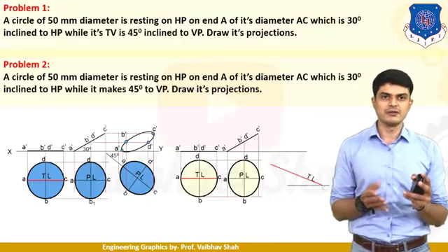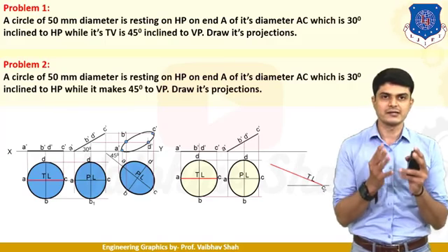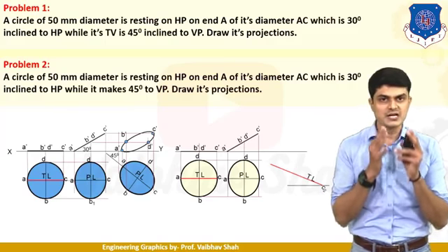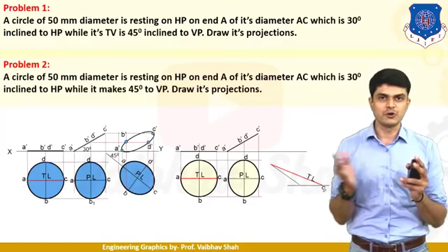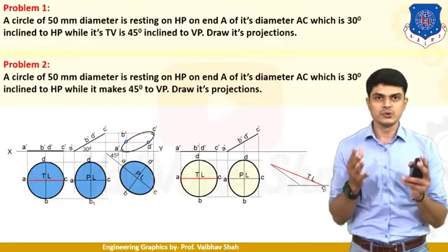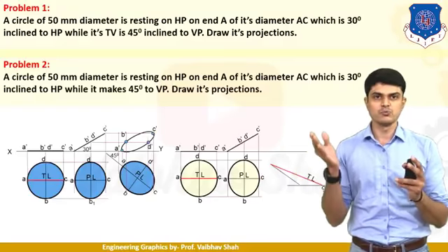After getting this true length, we will be marking this point as C2, because from projection of points we know that the true length end point is known as your point C2. After getting this true length, we will try to plot this plan length, because we know that we tend to redraw this figure of second stage into third stage in order to move ahead.